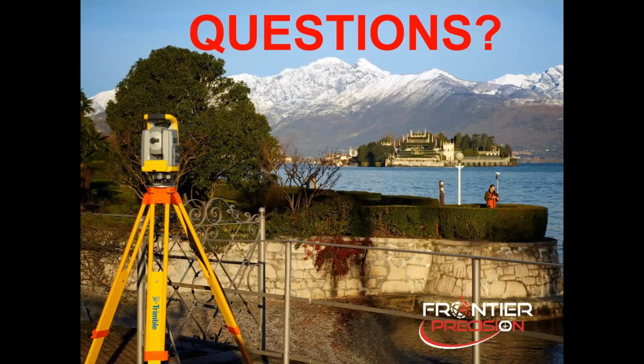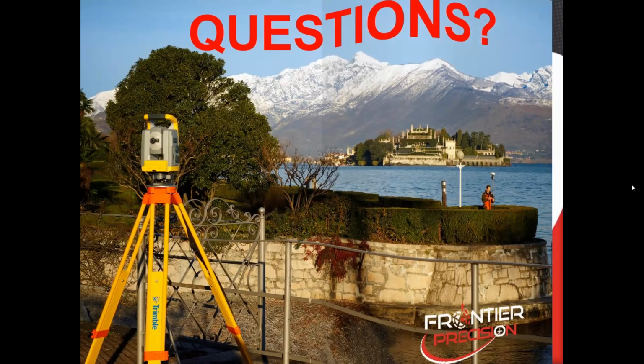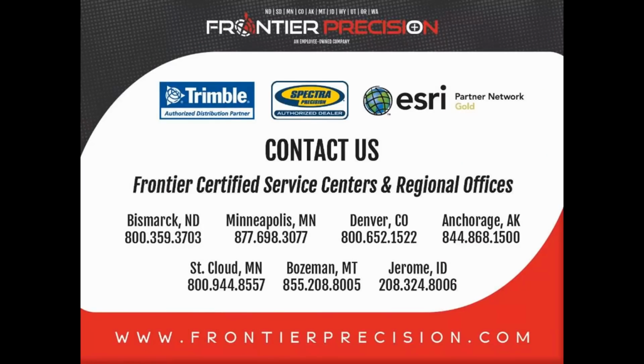Next new question, here we go, is what about the gray box Trimble target ID? Yeah, I didn't really touch on that. With the standard 360 targets, the little black 360 degree target, you can get these little gray RMTs, or target IDs. It's like a little gray box that kind of clips onto the rod extension, and it's powered, and you can turn it on. There is a setting in there for that. I haven't used one of those in quite a while, but I know that you can pick that and switch it to an active tracking mode, where I believe you can put that RMT number in there. Is that correct, Steve?